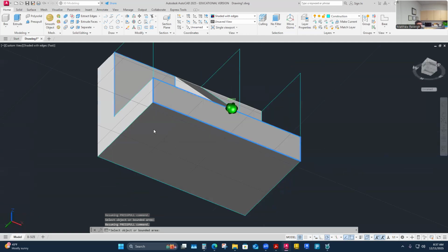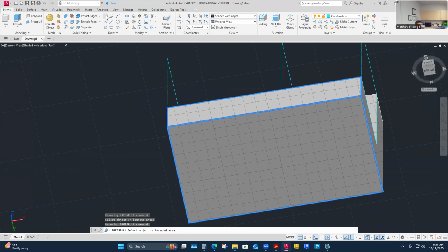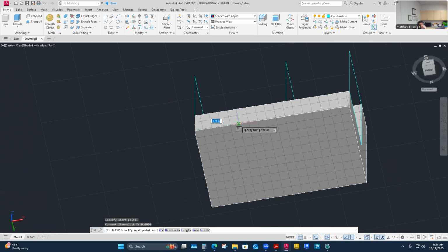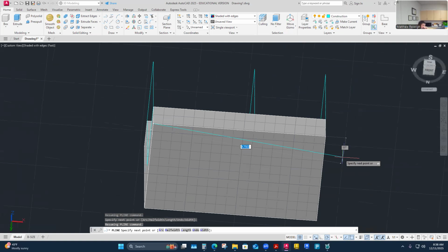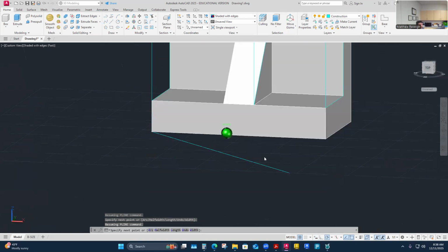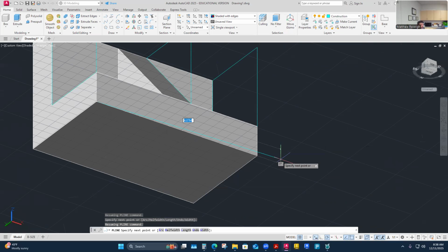on the bottom here, right? So it's just coming in 3/4 by 3/4. So I can do the same thing. Just draw a polyline here. Maybe I'll just draw it over this way, 3/4, right? Sometimes you'll see me draw this along. When I'm 3D sketching, it's weird because you can kind of not tell which plane I'm on, because of the plane that I've got shown here. And I've referenced this surface essentially. Even though I want to make this only 3/4 of an inch long, I'll pull it out past my object and make sure I'm on that plane.